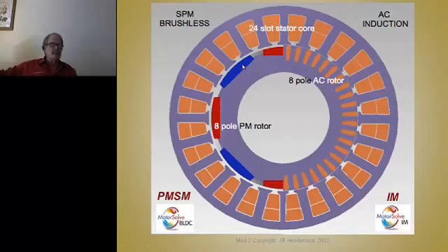The circuit is magnetized by the magnets, those magnets we bought, so we get that free magnetic circuit excitation from the magnets. So we don't care if the air gap's a little bigger. We're going to show you later what the effects of that air gap are. All it means is if I make the air gap twice as big, I just got to make the magnet a little thicker, and I get the same flux.